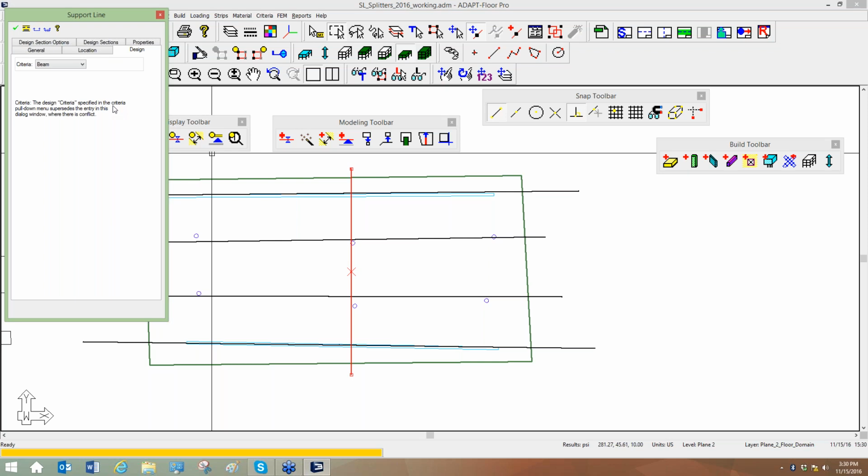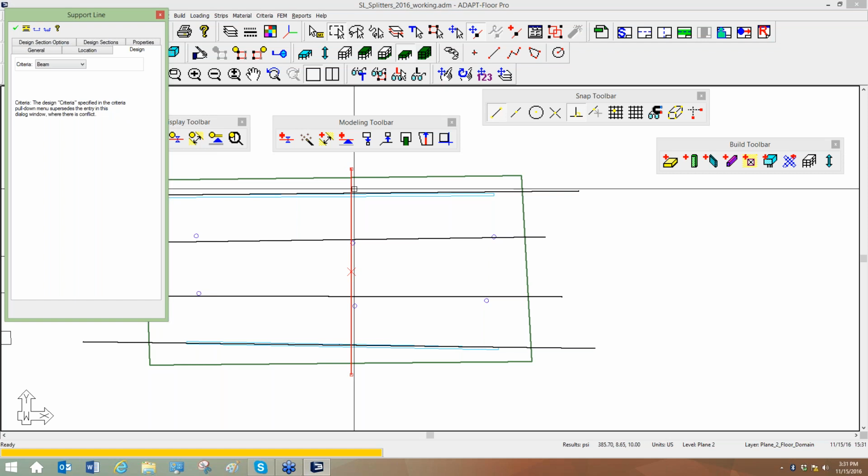For example, for a post-tension slab we apply 0.004 times the area in tension for one way, versus different requirements for two-way. So you could make the argument that it's behaving more one way in this span here, therefore I want the program to calculate the minimum rebar based on one-way action.